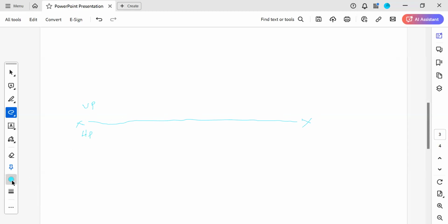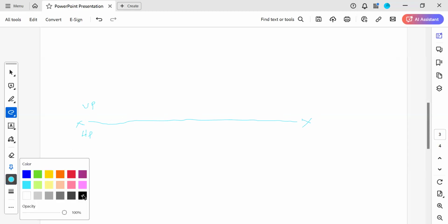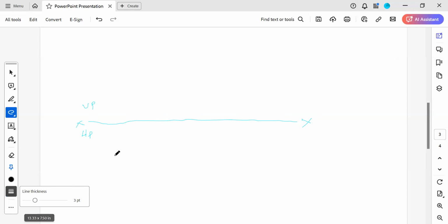Now you need to draw the pentagon. One edge should be perpendicular to the xy line. So draw a 30 mm line, 3 centimeters. At this point, measure a 72 degrees line.